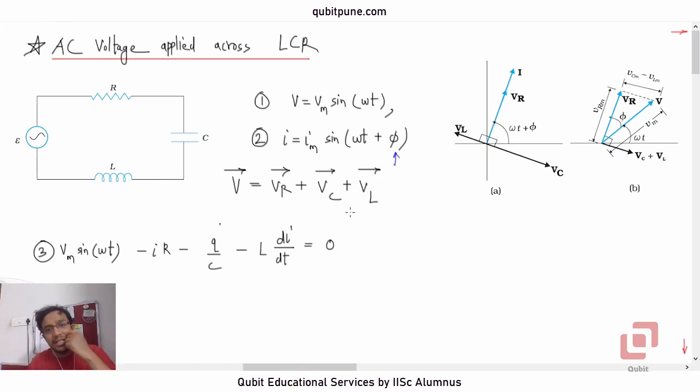Now while showing these things on the phasor diagram, I'm going to remind myself that the current will be the same for all three, because they are in series. The current will be in phase with VR. Correct? The current phasor will be in phase with VR bar, and you can see the coincidence of the current phasor and the voltage across resistor R.